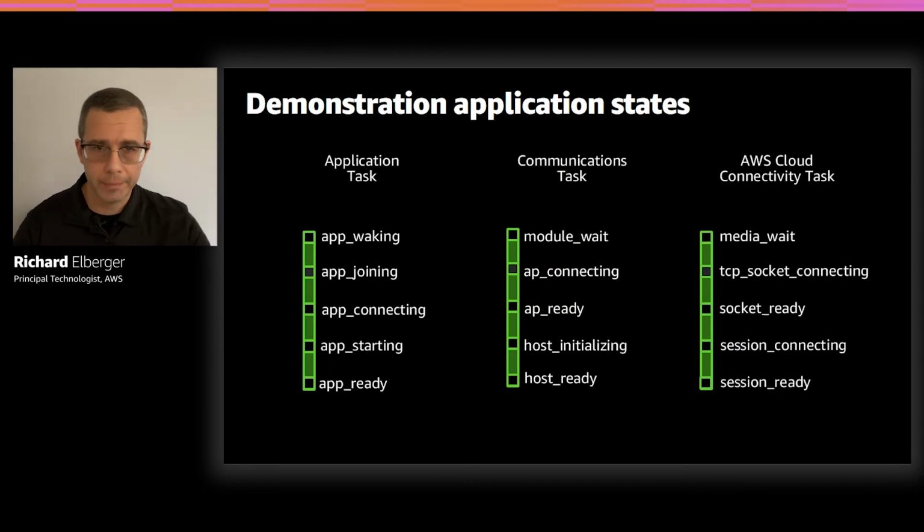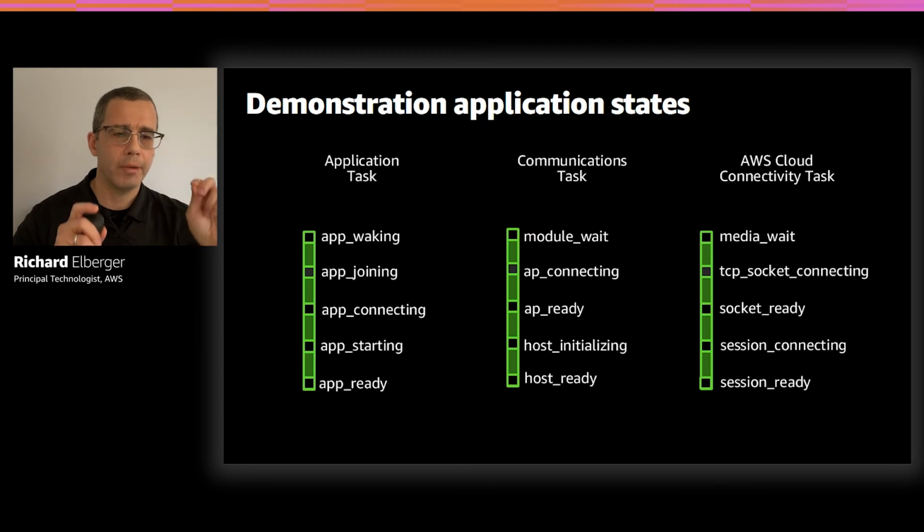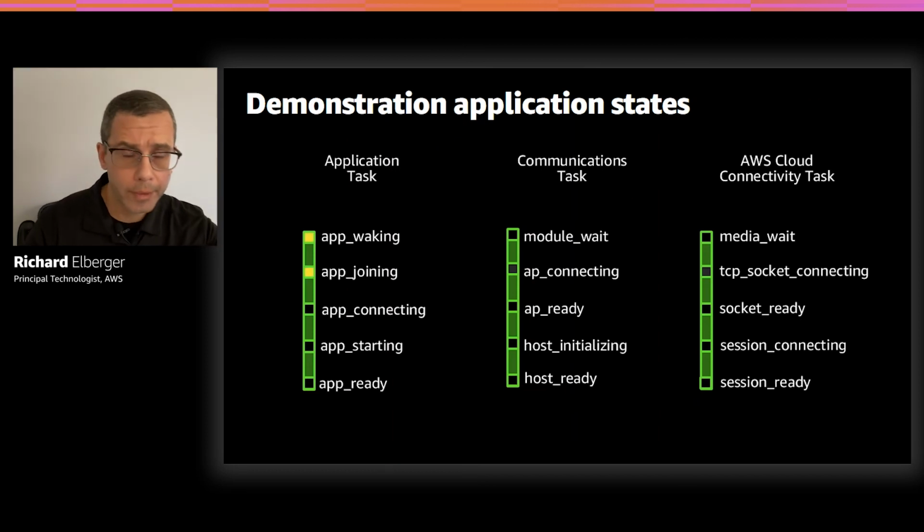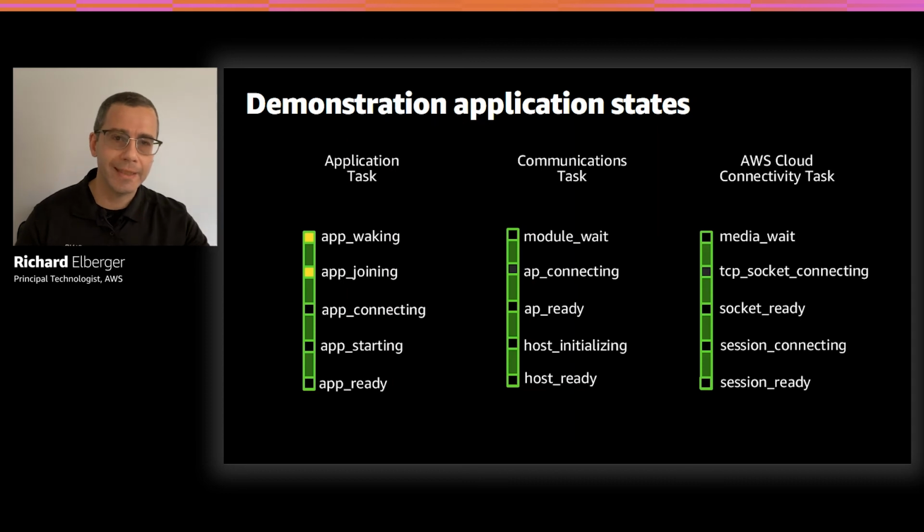Of course, there will be the MQTT task, which you'll build in your sensing stuff, or we can call that an agent, right? It's just going to keep on running. But let's focus on the connectivity right now. The two tasks on the right are actually the same tasks, but two different state machines. So that task is started, but we're waiting or blocking on a notification. We're going to walk through this as if connecting to an access point. The app wakes up, right? And either by initialization or coming in from low power mode, the application sends a notification to a task that says, hey, start connecting, and then it goes to work. Then it goes through a series of steps, right, to connect.